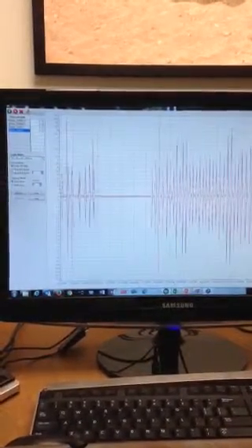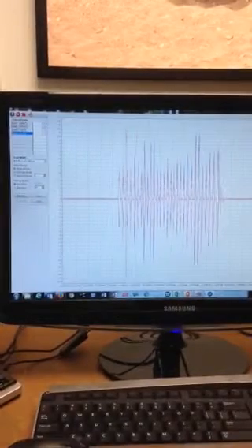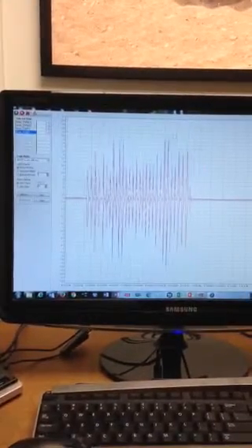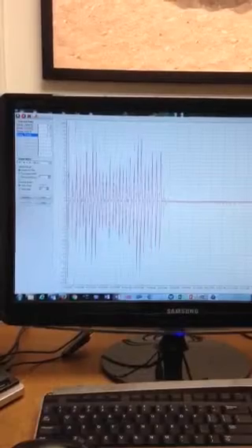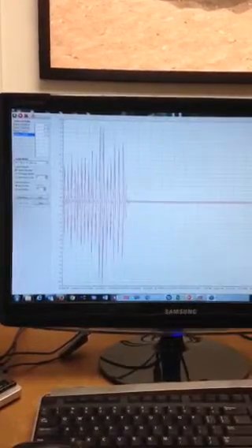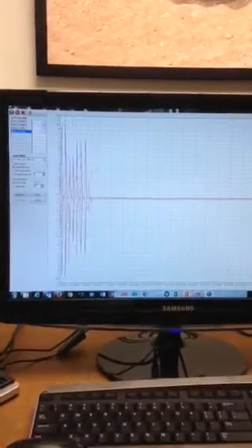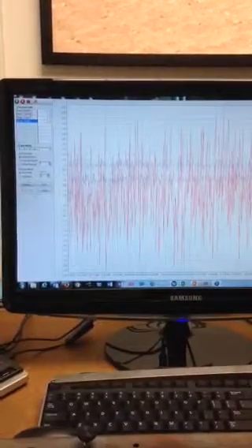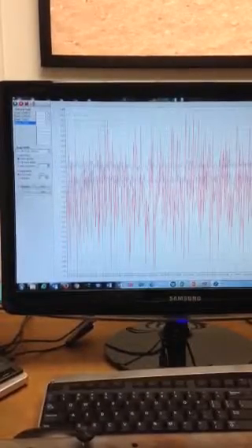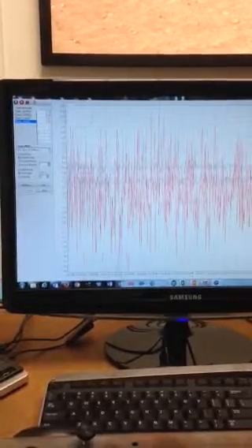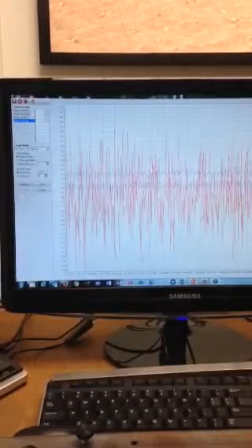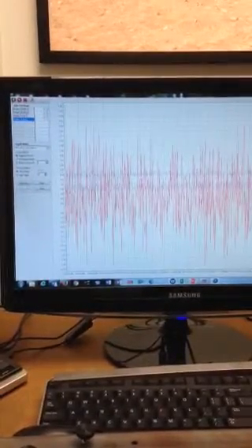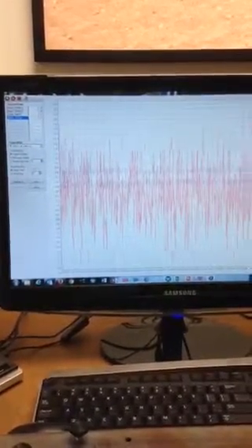And please again keep in mind that the reason for the drift is that neither the vibrating wire gauges nor the bonded foil gauges are thermally compensated. And there we see the drift, especially on the, yeah, it looks like all of them are tending in a positive direction. So, all right, that's it for the video.